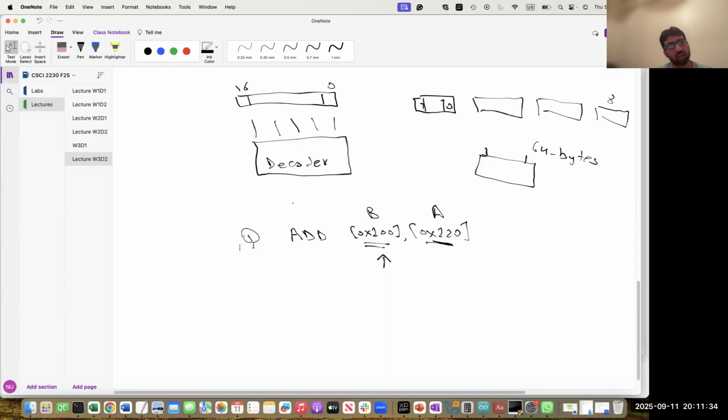What we are doing in the AVR microcontroller and RISC architecture is first loading data from memory into the registers, and then from the registers into the ALU. If you want to read data directly from memory into the ALU, your design will become more complex, and not necessarily faster, because you will be accessing memory. Again, it depends where your memory is located, on chip or off chip, right? But even if it is on chip, your design will still become more complex.